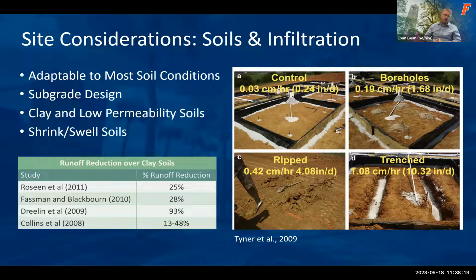You probably want to avoid any shrink-swell soils, because this will create instability issues. But if we have clay content and we don't have shrink-swell soils, we can work within those situations if we can get up to 1/2 inch an hour. Or we can allow for whatever passive infiltration occurs and have an underdrain that takes any excess away.